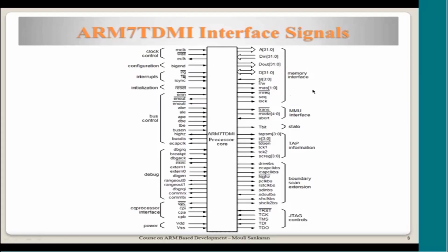Now, why are they not giving any pin numbers here? Again, the reason is that this is not coming as a single chip. This is an IP, intellectual property core, which is going into some other SoC. So these signals will be going into some other modules within the chip, and then those signals come out of the IC.